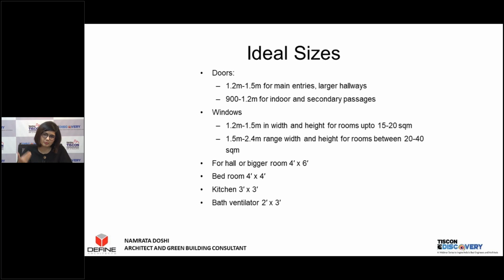So it's either opening up into a courtyard, a garden, or any kind of open green space. Any of the bedroom windows, if not directly into the open space, should at least have 3 meters of open space in front of them.